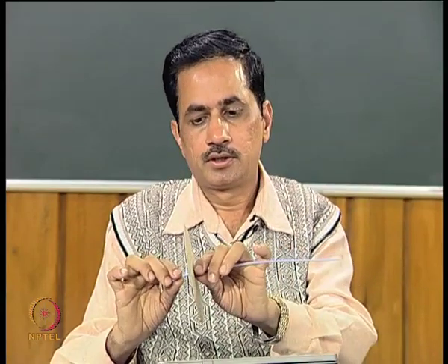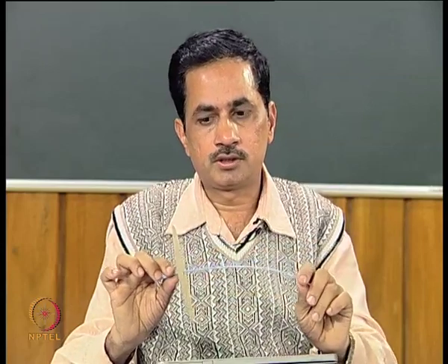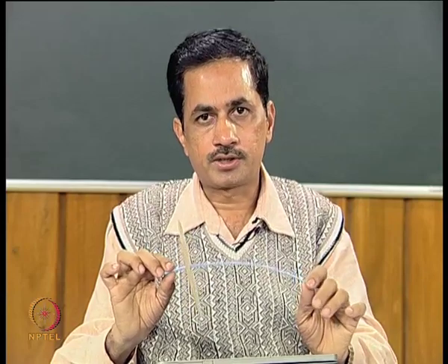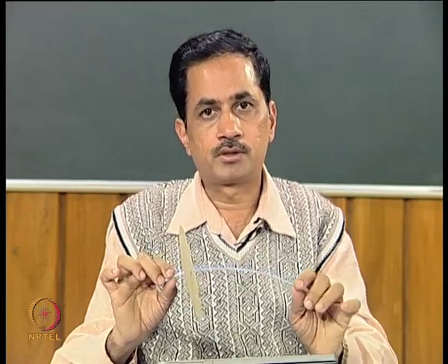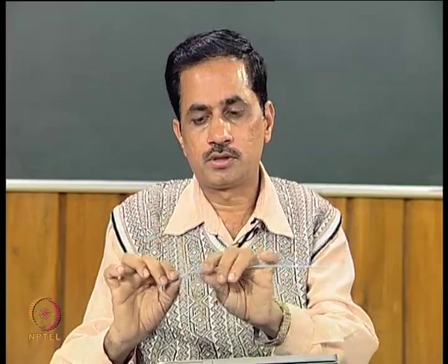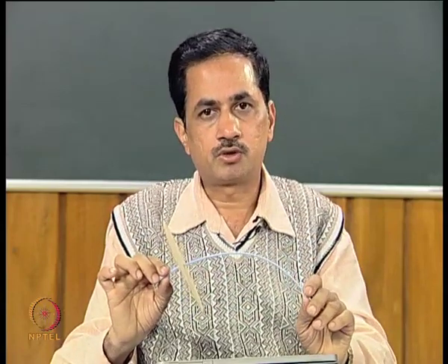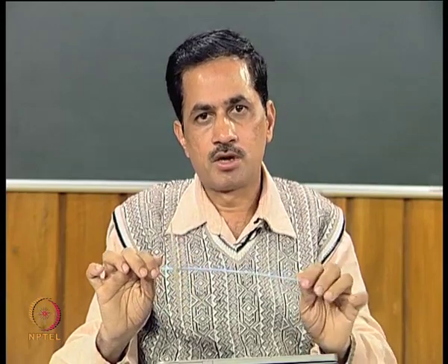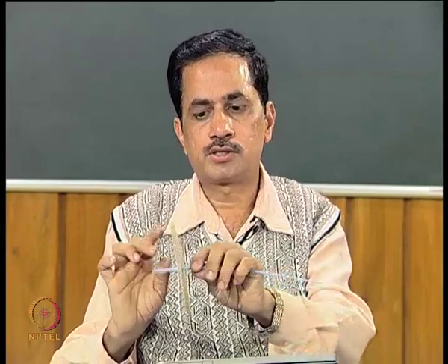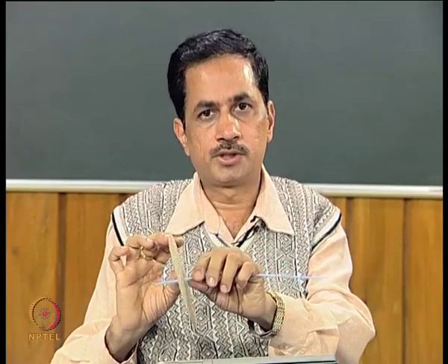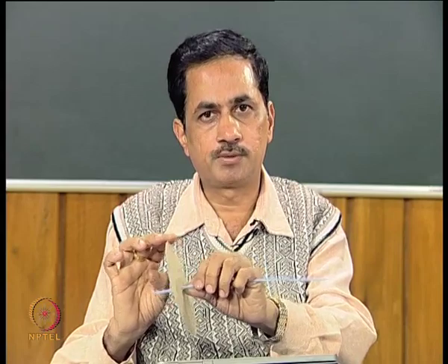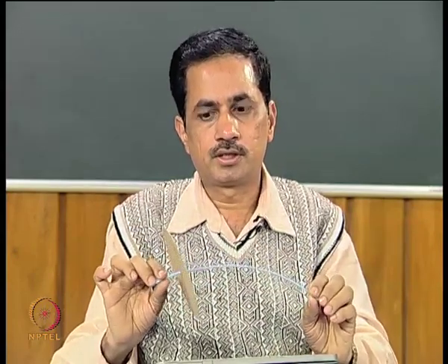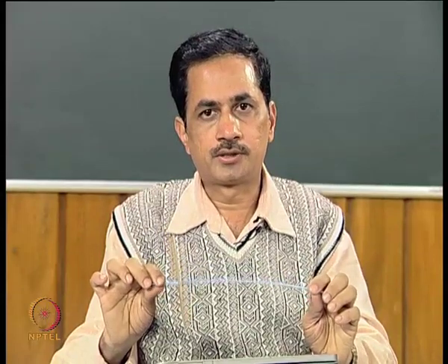In the subsequent topics, we will see this particular kind of wobbling not only introduces additional degrees of freedom, but also it introduces the gyroscopic couple, because this particular disc is spinning about its own axis. Now because of this it starts wobbling. So there is a precession of the disc also along with the spinning, and because of that we find that gyroscopic couple will also be there.